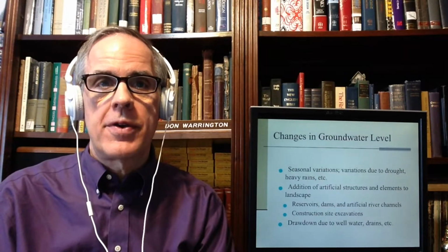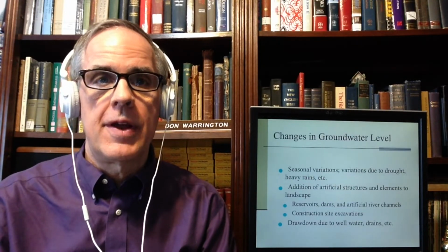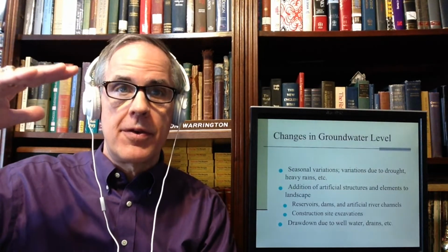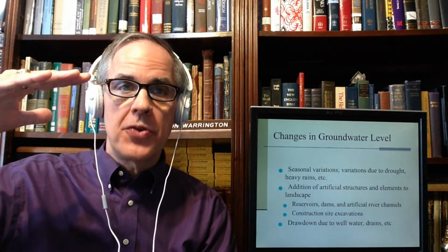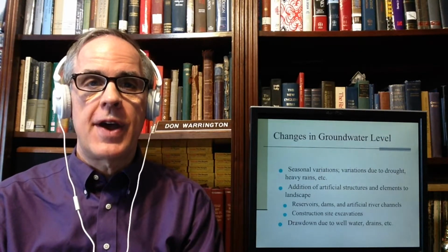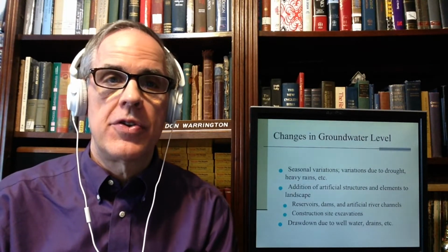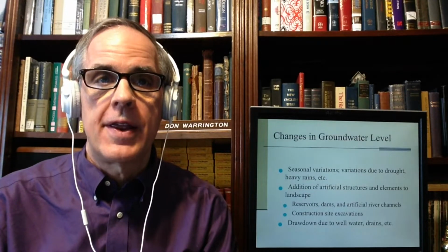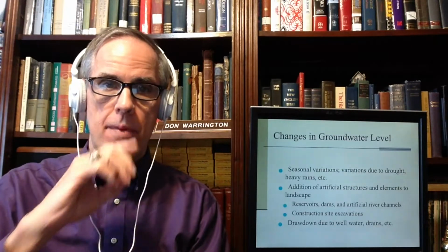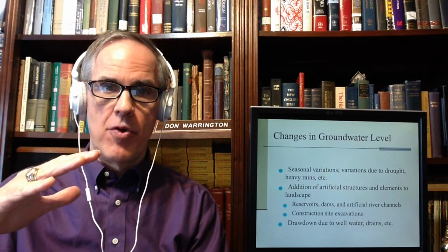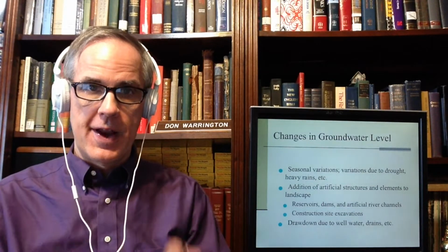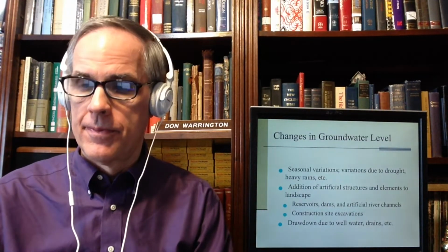We normally talk a lot these days about sea level rise, but before that, we've had to deal with problems of coastal level drop due to subsidence. And subsidence makes coastal areas more vulnerable to flooding. By taking the water out of the ground, it's a form of compaction where we pull the soil particles together and they drop.